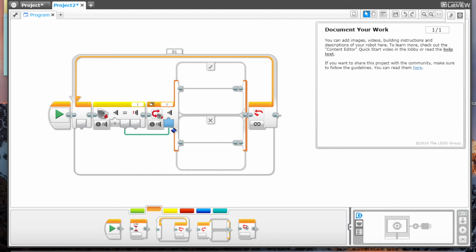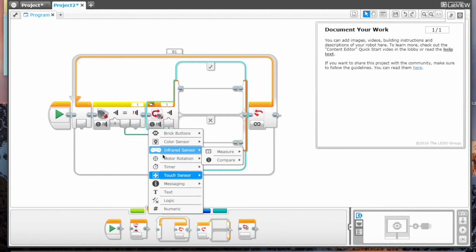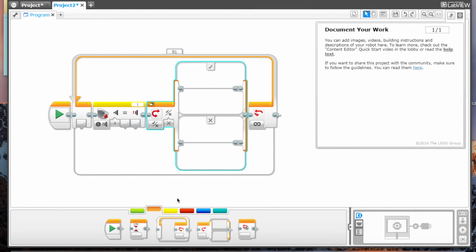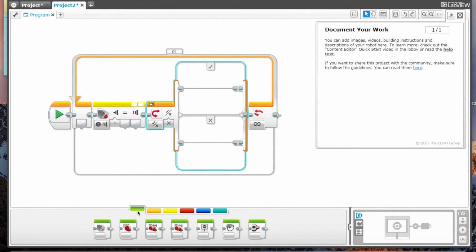Don't forget that running the program like this will result in the robot moving right from the beginning. This is happening as it already detects the sensor button as released, so you need to push the sensor button before the program starts loading. This way, when you release the button from the sensor, the robot would start moving. Give it a try, it should look like this.